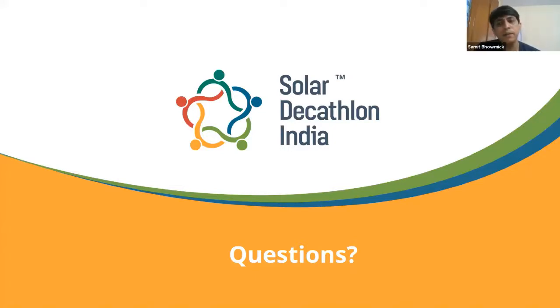Maybe I'd like to add here, there's a spreadsheet along with the self-learning module also, but the spreadsheet lists all directions of orientation. You don't have the sun on all sides at the same time. It's peaking on one side at any point of time. So there is one point of time when the cooling load actually peaks for that particular building, and therefore you need to estimate for that particular hour so that your equipment is not undersized. Correct.